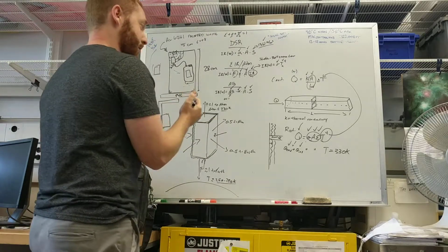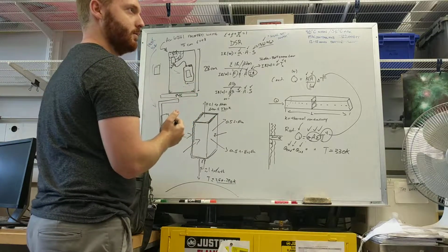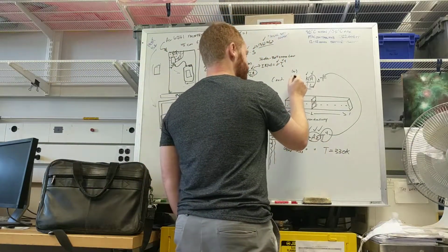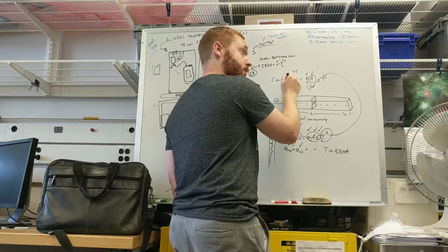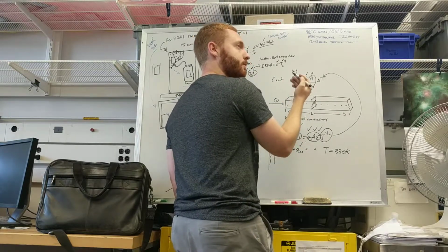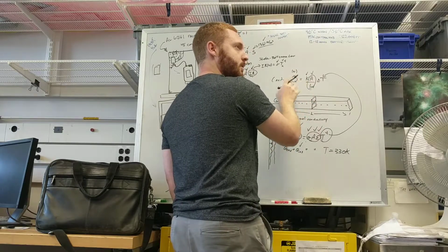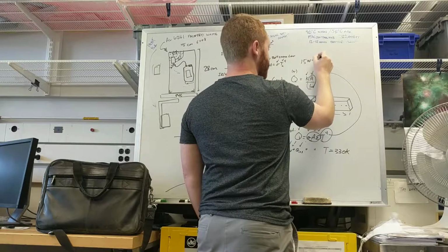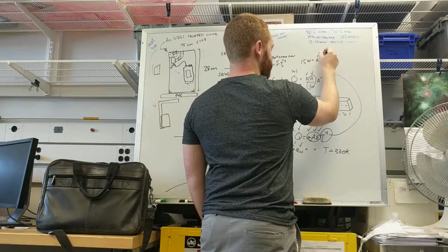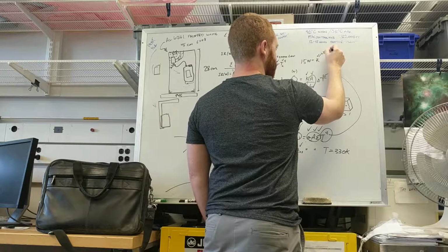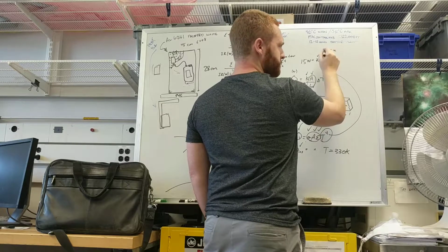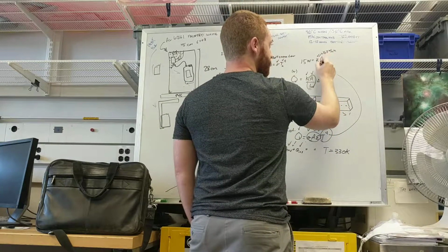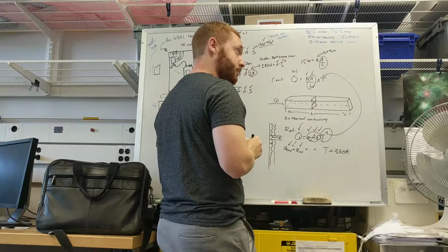By default, that means your electronics are going to be warmer than 330 Kelvin, right? So what you do is you come up to here, and you have the Q. So this Q now, because it's only conduction, only deals with the heat that you're moving from the electronics. This doesn't take into account any of the external stuff. So now I'm trying to move 15 watts, and I know my K for aluminum, which is about 167 watts per meter Kelvin. Sounds right. And then the A over L ratio is something that you're going to have to design and optimize.